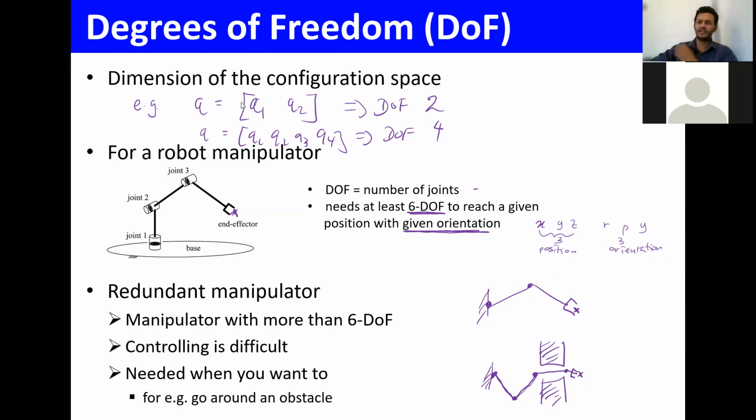So if we take, let's say, the right hand, okay? I hope you can see. Here we have the shoulder joint, which looks like a universal joint, right? When I say universal joint, that is like 3 revolute joints in the same place, right? So we have 3, and here maybe, let's say, only 1. So 4, and how many here?